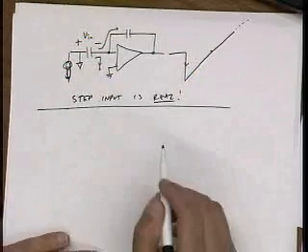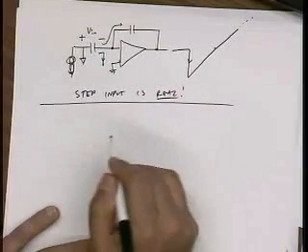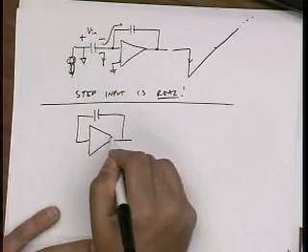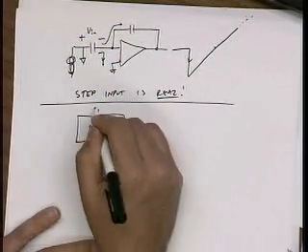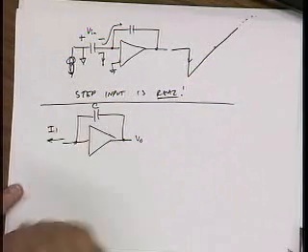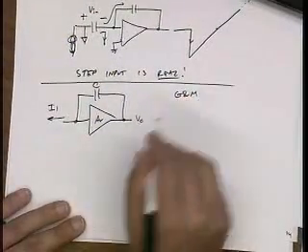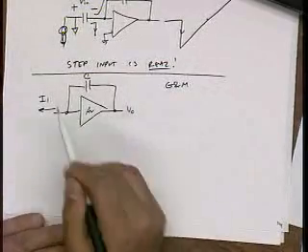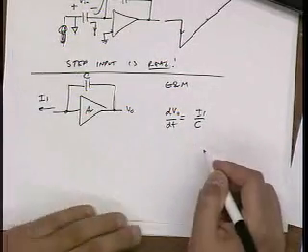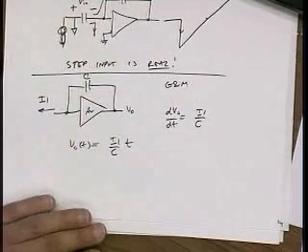Okay, if you look at some classic books, they always try to relate the ramping behavior to some small signal parameters. It's kind of useful to do that because it gives us some insight on how we might improve the slewing in an amplifier. So here's a simple model. I have a fixed current, call it I1 for now. I'm going to be consistent with Gray and Meyer notation. It's going through this integrating stage, and we know that the output will ramp proportional to I1 over C. In other words, we have this linear ramping.